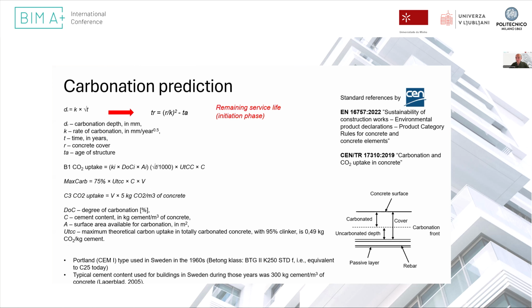Due to brevity, I will not go into detail on the calculation methods, but you can look into the paper. There's a standard for environmental product declarations on how to calculate CO2 uptake in concrete by carbonation, and also a technical report related to the standard. We rely on the square root of time model for the simplified model, which is a generally acceptable model for concrete service life and CO2 uptake, widely used in the literature and also validated by previous research.